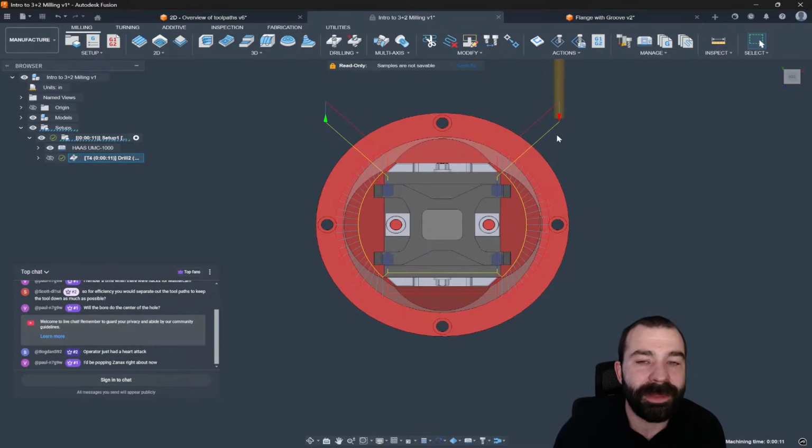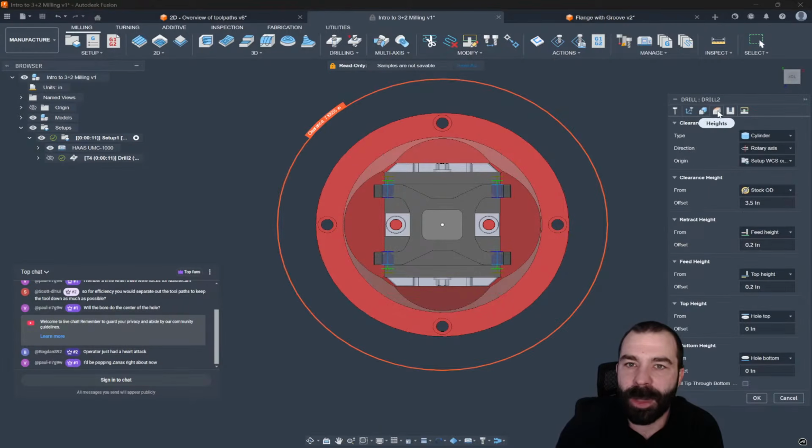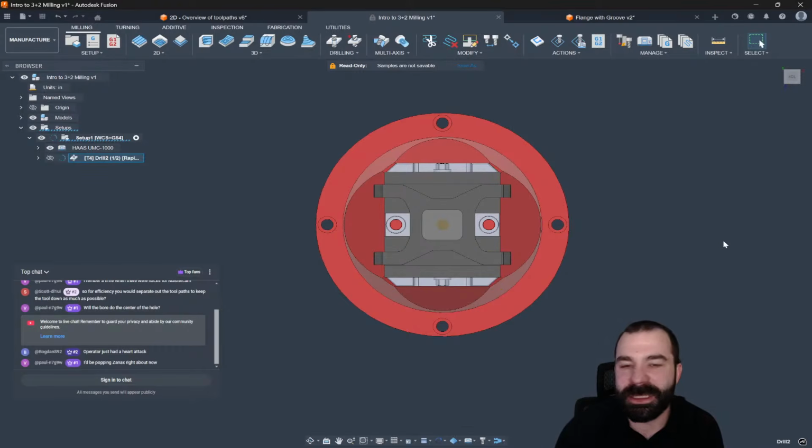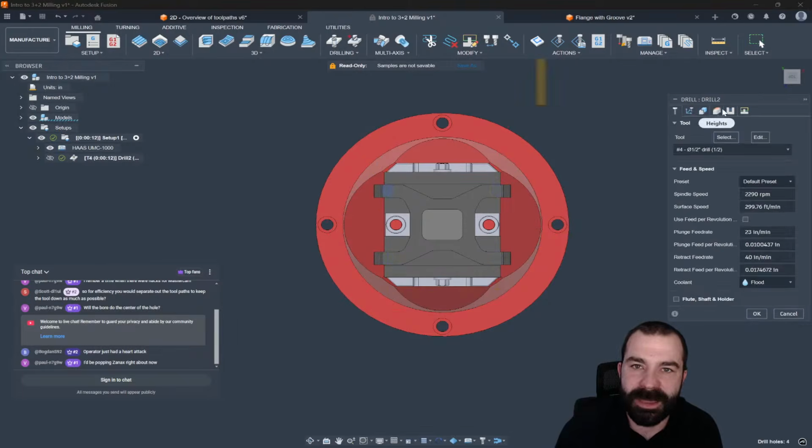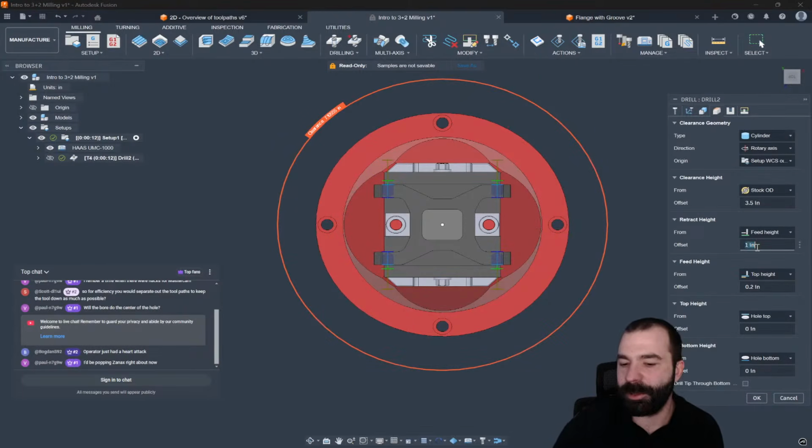So this is another key element when we talk about changing up to the cylinder or sphere method, is our toolpath is now coming from the shortest distance from that boundary. So it wasn't necessarily clearance in this case. Our problem is actually more around the fact that our retract heights are not far enough out. So I may need to change that to be, let's say, 1 inch. As you're going to notice, if I go to 1 inch, we're much further out when we start that swing. I could increase that even more. So let's say we're going to go 3 inches.